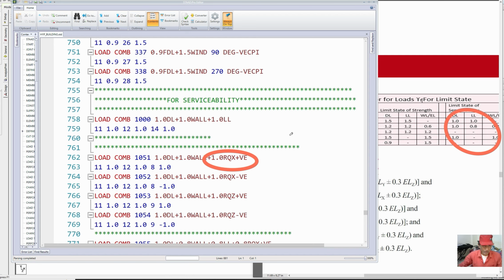Analysis. This is because for strength design, the base shear has to be scaled up to match up. The dynamic base shear has to be matched up with static base shear. But for displacement estimate, we do not require to scale up the base shear, and we can check the permissible deflection with respect to the displacement estimation obtained from the dynamic analysis with a scale factor 1.